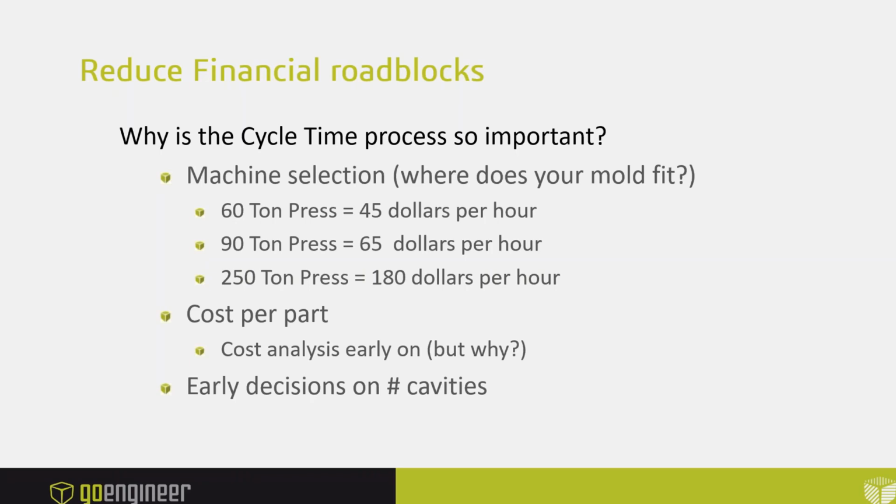Like if our target goal is a quarter and they're costing $1.20 now, how many cavities do we have to make this part come in at an effective price? A 5-cavity mold, right? So that would justify our financial decision to say, hey, let's go from 2 to 4, instead of 4, let's go to 6, or instead of 4, let's go to 8, so we can get these piece prices down below a quarter.